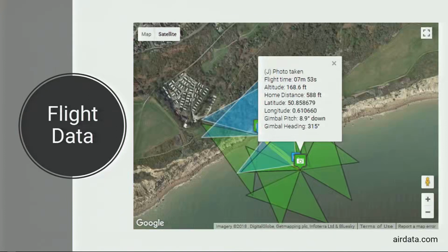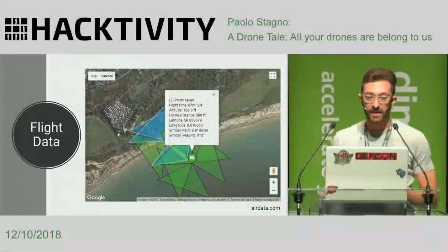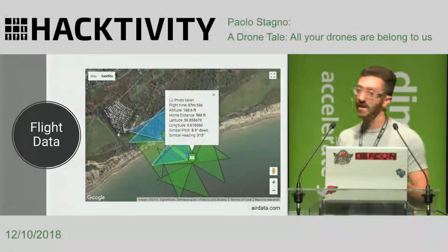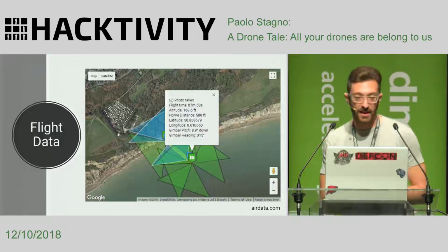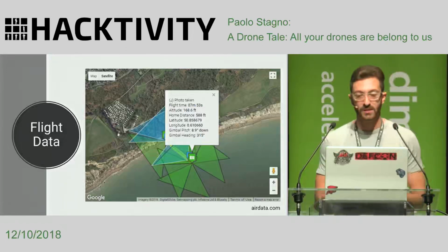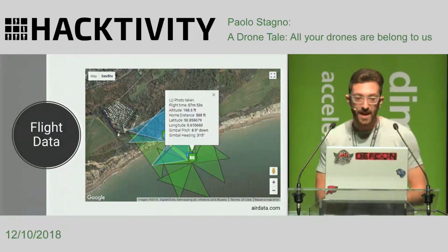So if we intersect all data, basically gimbal data, flight data, and the events in which photos or video are taken, we can also reconstruct this kind of map that can show us what the operator was able to see and photograph. So we can be better than CSA.